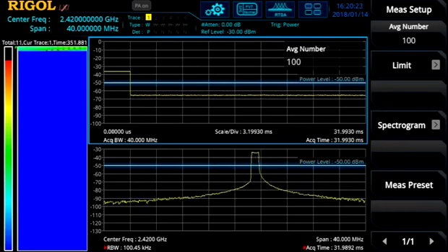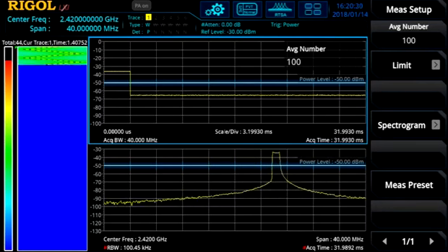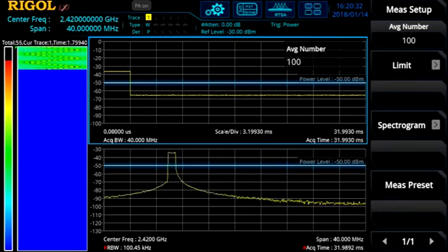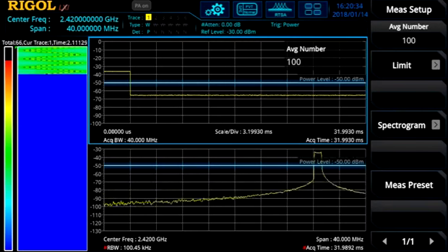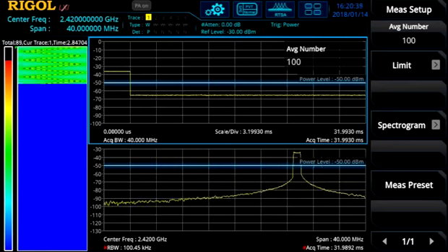That's really the power of real-time spectrum analysis. This shows that each pulse is 3.2 milliseconds long, with one FM modulated pulse at each of the 11 frequency channels. So there are your techniques and visualization tools in a real-time spectrum analyzer for debugging frequency hopping signals.